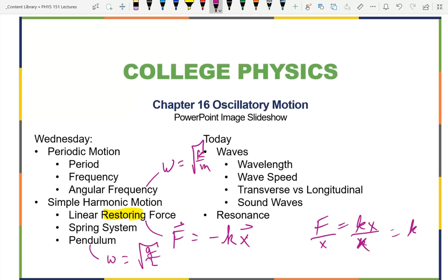Now, I forgot, I want to talk about a couple of things on the test. First thing is units. A lot of people missed points because they didn't convert units. For instance, there were people who tried to use Fahrenheit units in the ideal gas law. It has to be absolute temperature units to use the ideal gas law because it's not a change in temperature, it's a temperature.